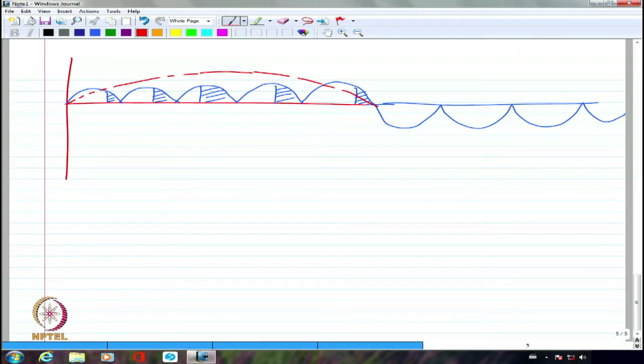So it is the same thing I will be doing in the negative half cycle as well. So I may get only a small voltage, this is a little larger, this is much larger, and then I'm going to get smaller and smaller voltages. Get my point? So this is also going to approximate this entire thing to a sinusoid somewhat like this. So I can control the output voltage approximately to a sinusoid. It is not a perfect sinusoid. It is only an approximation to a sinusoid.